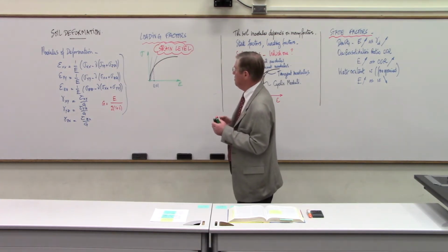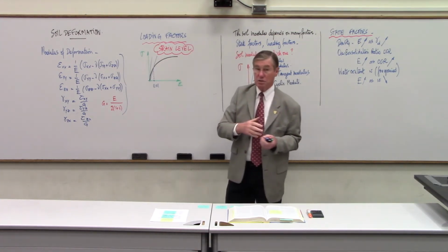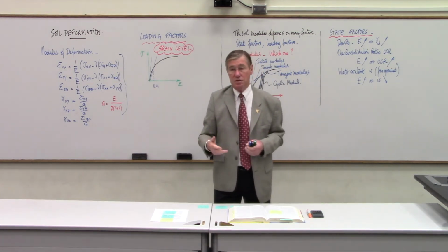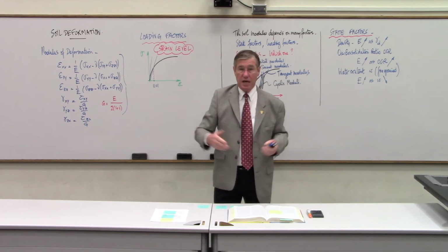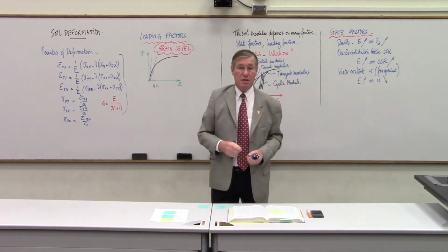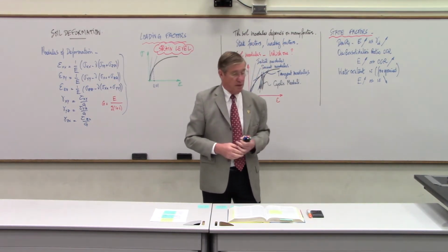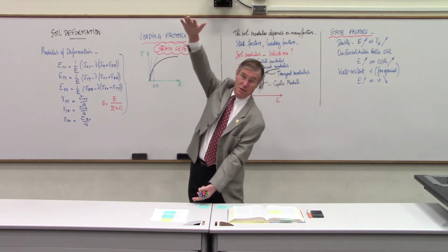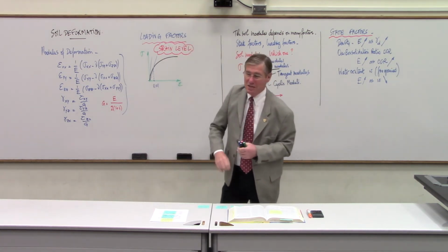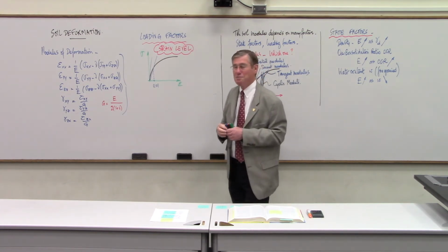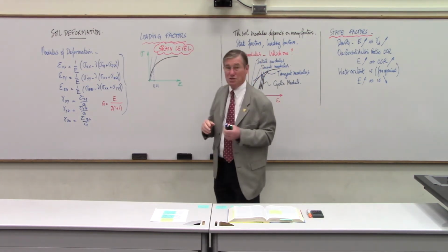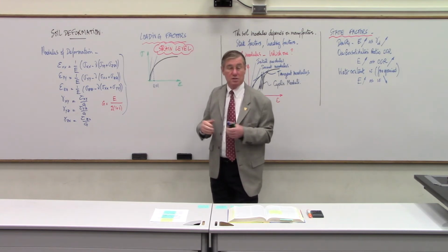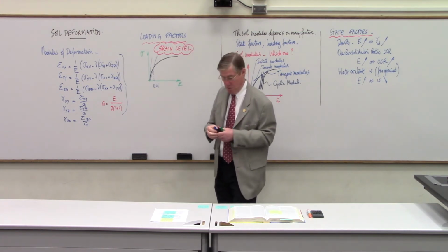And sometimes we have embankments that we build next to rivers, and the material is relatively soft, the embankment is fairly high. There's a significant amount of settlement. We talked about, in the last lecture, the Washington Monument settling about this much. Now we're talking about some serious strain. This was not intentional, and you don't want to design foundations to that large strain, but there are some embankments that settle several meters when you build them.